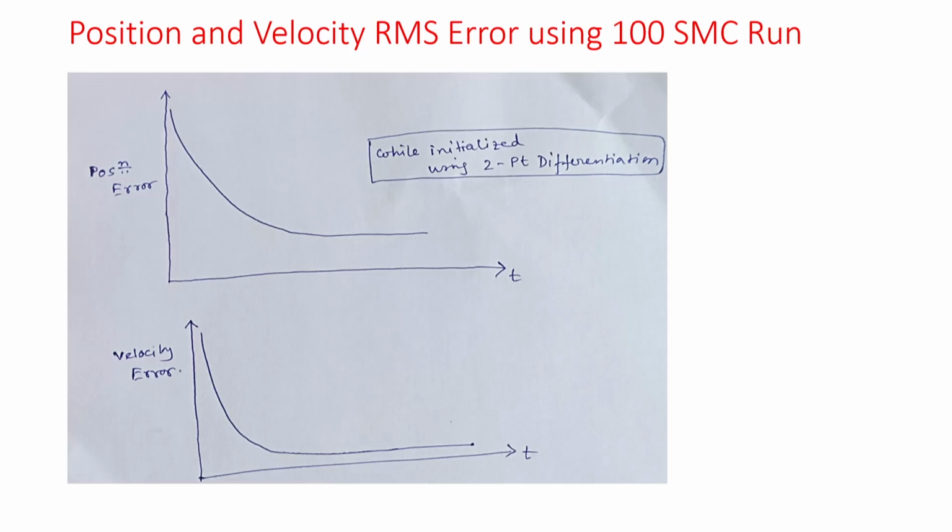In that case you won't have range measurement, you will only have the bearing measurements with you. So, still can you use Kalman filter? We will see how we can use the pseudo-linear filter. Some cases you can use, some cases you won't be able to use. With this, now we will go to the bearing angle only measurement problem.